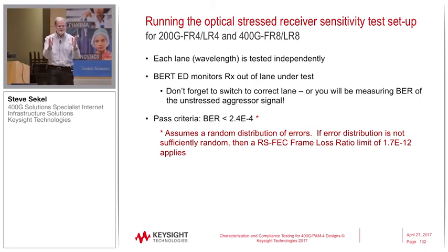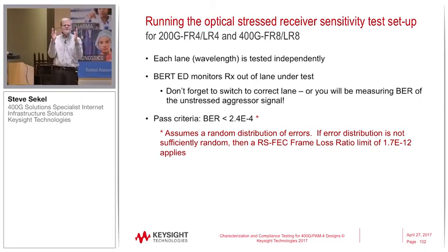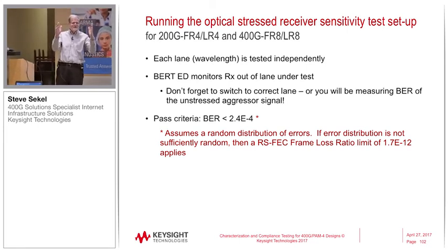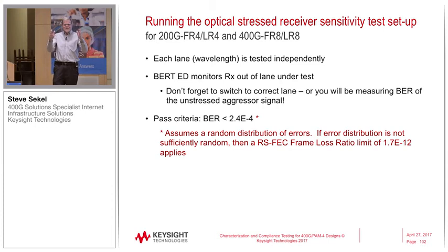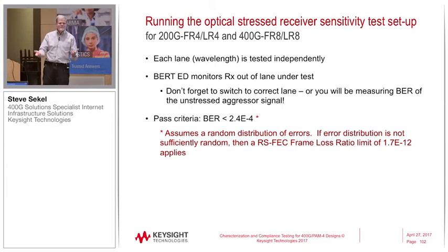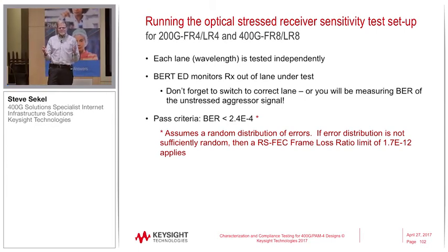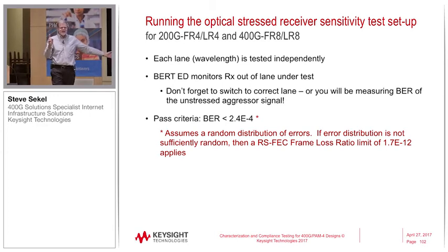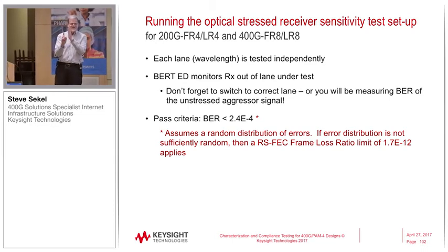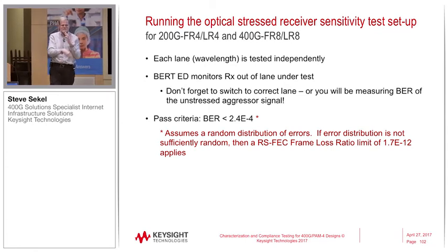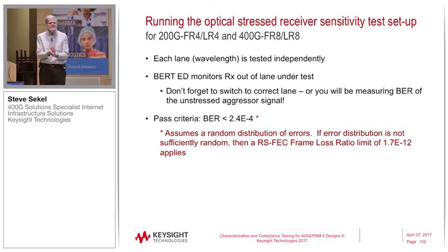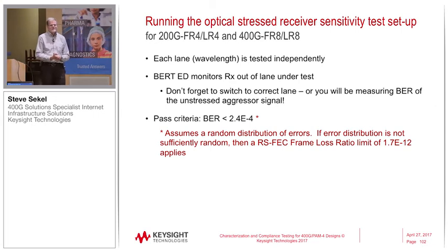And the only time you get a frame loss is when those errors, and it's not necessarily a burst of adjacent errors, it's just within that frame, okay? If you use error location histogramming, pattern position histogramming, I'll try to avoid using the trade name, then you could have one pass to the pattern where we get one error, then 1,000 passes of the pattern error free, and then another pass where I get an error right next to it. Now I start seeing that histogram go up with a whole cluster of errors in the same place, but those are not necessarily in the frame. It indicates a likelihood, but not necessarily a guarantee that that was a real frame loss.